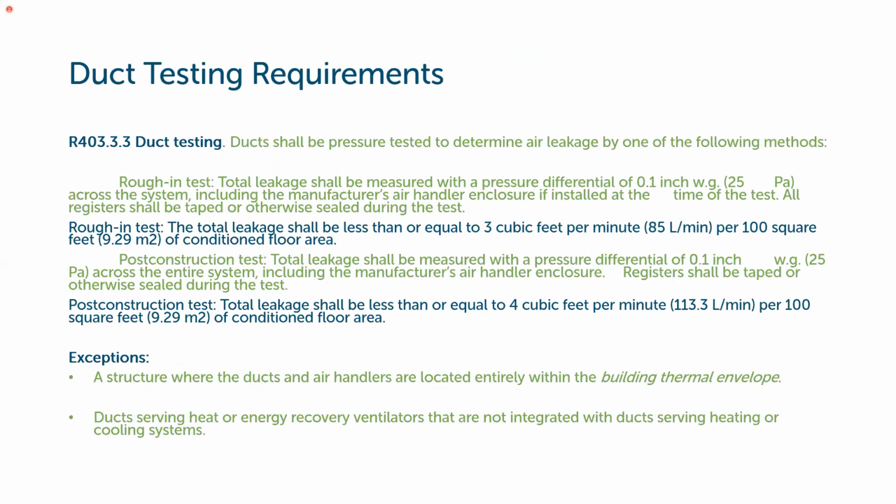So duct testing is required for ductwork that is outside of the thermal envelope of the building. So you have two options for testing. You can test the equipment at rough-in, before the building's complete, or you can test the building at the very end when everything's all done. There are different leakage requirements or maximums for leakage through the duct system based on those two options of testing.